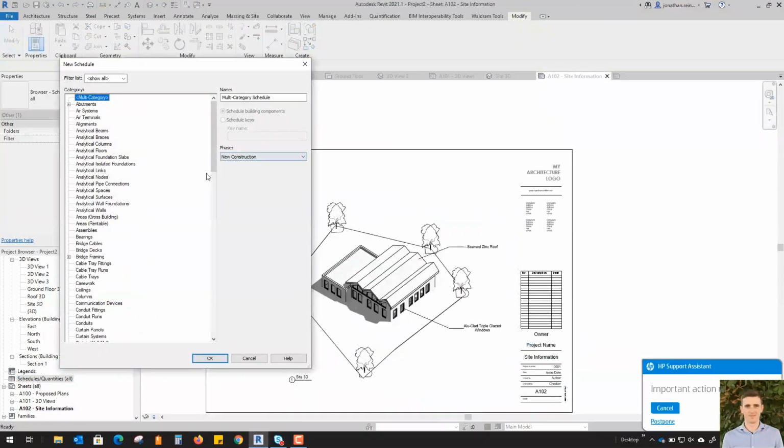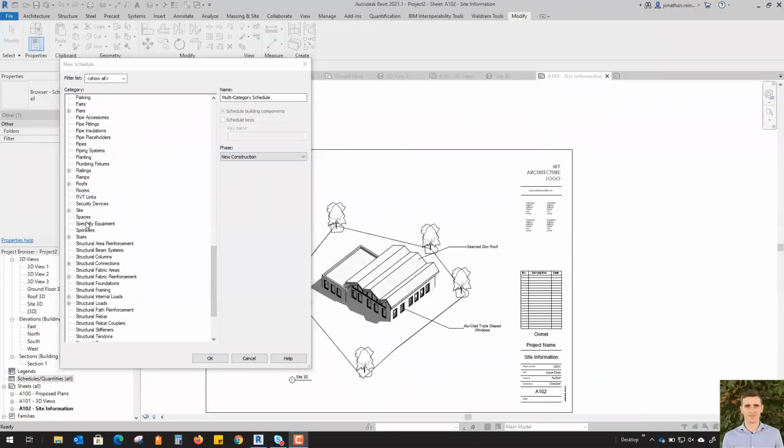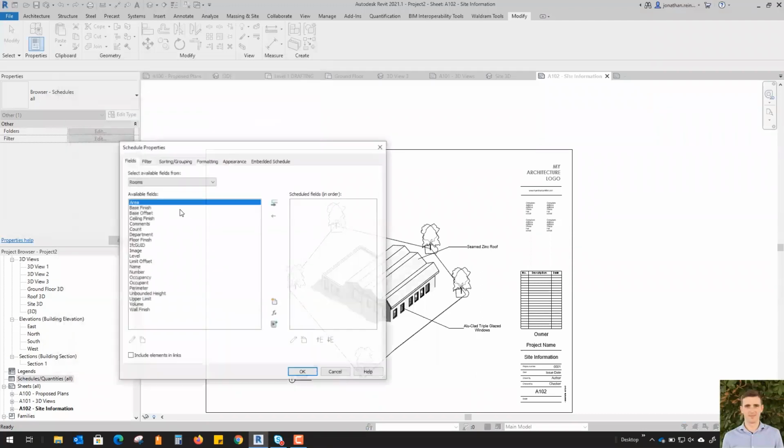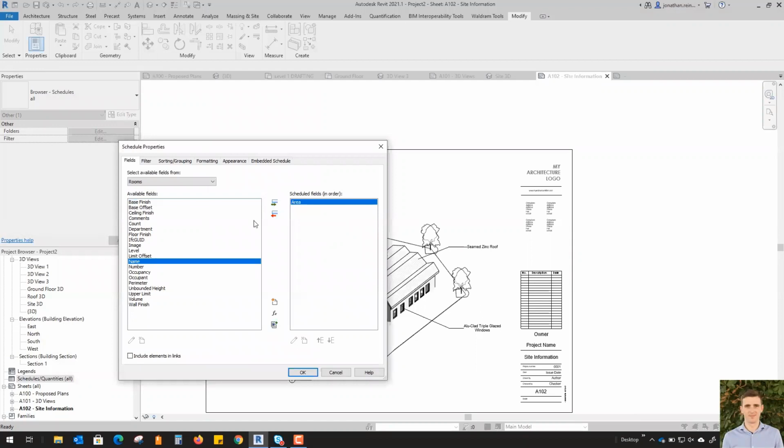Leveraging the building information in your model is also very powerful. So what we're going to do, we're going to create a room schedule and place it on one of our sheets. So we're just going to capture all of the floor areas and the room names, and in fact the department types that we captured earlier on or inputted earlier on as well. And we're just going to place them into a table, also known as a schedule, and we're just going to place this on a sheet.